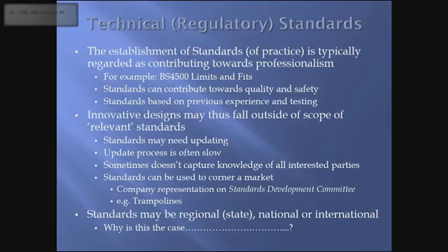Either you have a choice. You can use the NZS, the Australia-New Zealand standard, when it comes to steel buildings, or you can use the American standard. So what the engineers did was match those Chinese certificates, the mill certificates, to see whether the steel would fall in grade A or grade B or grade C, right? And for a building that tall, with that bearing and that load, that wind force, and remember we've got a lot of salty air, that particular standard has got to be A grade. So they had to prove that this can meet A grade standard.